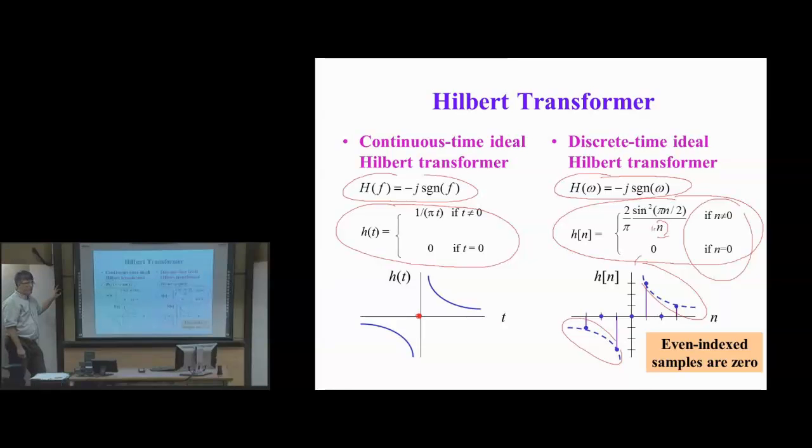We shifted it, but before we shifted it, we windowed it, is what you said. So we're going to truncate, and then delay to make it causal. And the delay will cause the phase now to be linear phase. That's what we'll do in practice.